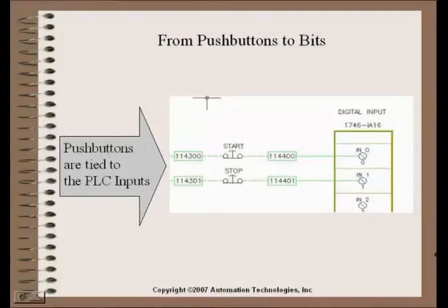So what's the difference between the PLC and the regular hardwired option? Well, with hardwired, you saw we take our push buttons directly to a relay, and it acts directly upon that relay. With the PLC, our start button comes into an input card. It's wired directly into cards that interface directly to the processor through a rack or some other means.